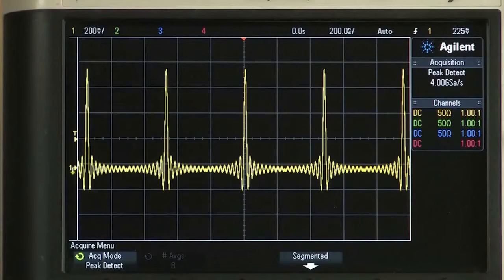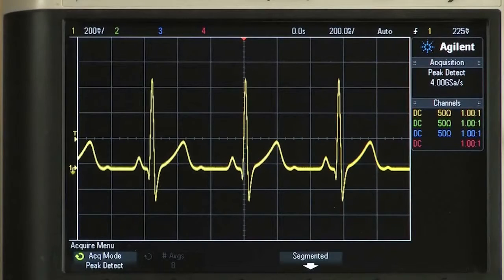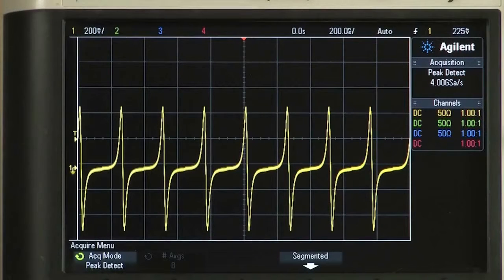A unique feature called sum allows you to easily generate dual-tone, multi-frequency communication signals by summing 2 frequencies together. You can define any waveform shape and length using the Trueform arbitrary waveform capability. Arbitrary waveforms of 4 million points per channel, or optionally 64 million points per channel, can be generated, with sample rates as high as 1 gigasample per second.